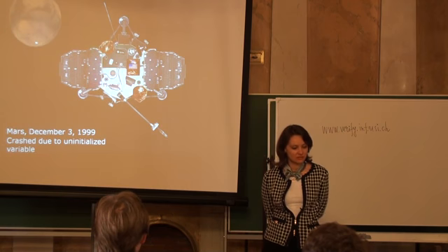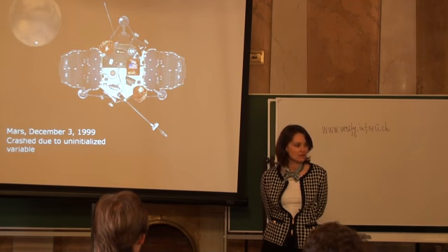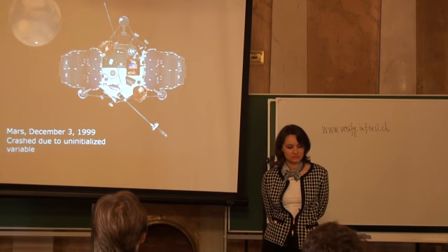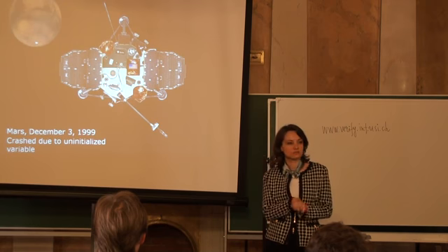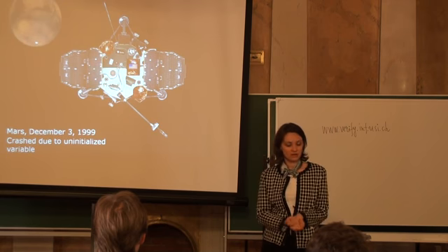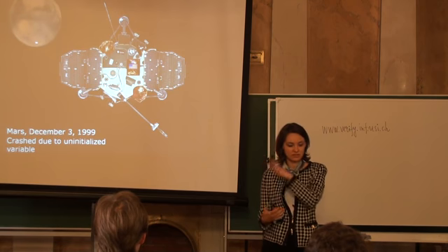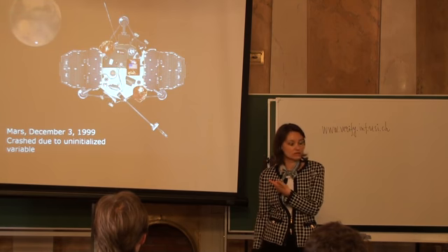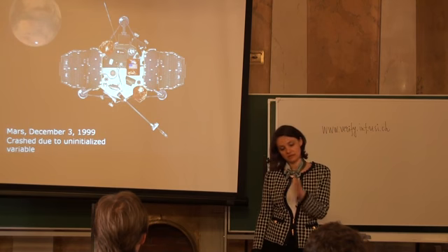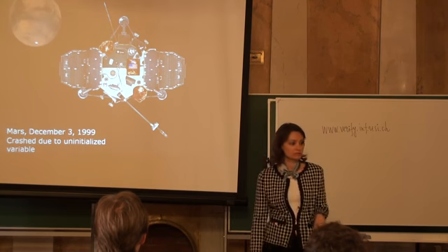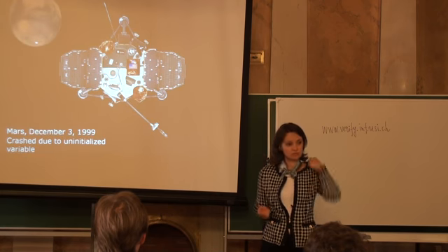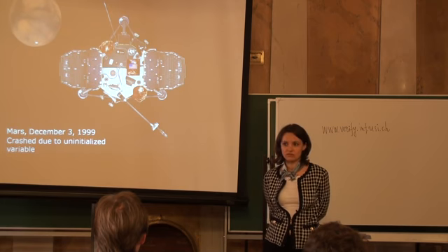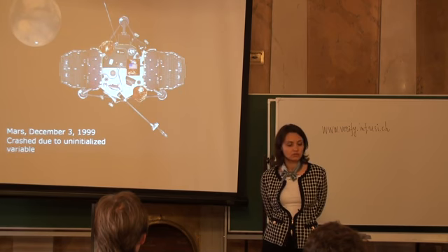Essentially, when it approached the planet Mars, it started getting into vibration mode because the pressure was very different. Because it approached the planet and the device started vibrating, the controller interpreted it as the device having landed on the surface of the planet, and it simply did the right job. It cut off the engines, but it was still several hundred meters above the surface. And because it cut off the engines, it fell, so it crashed.